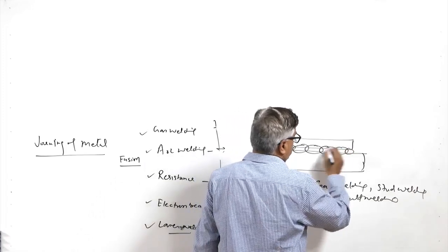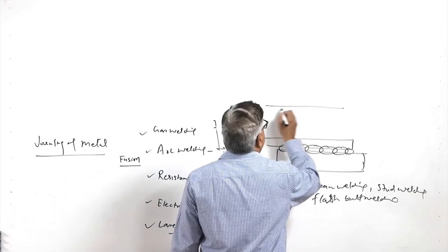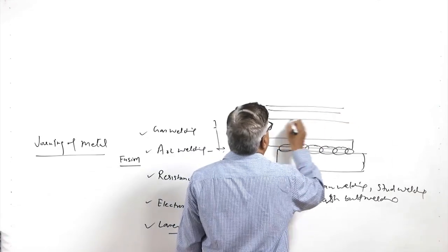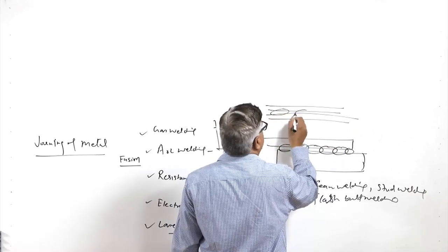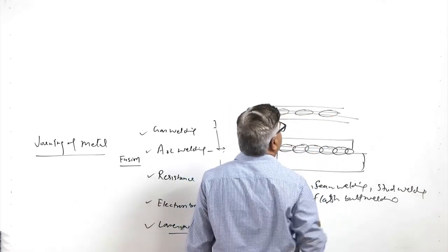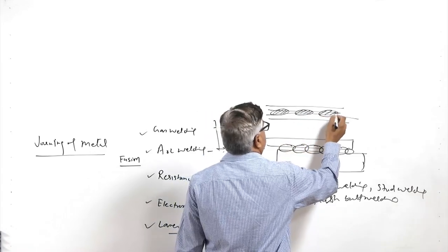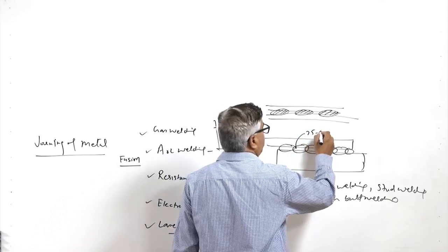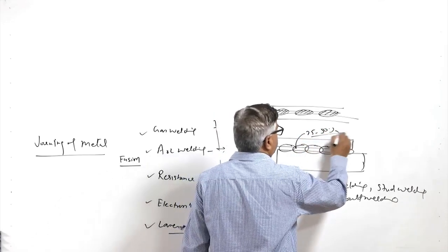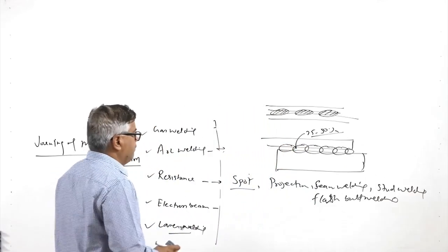A continuous seam or an interrupted seam, with interrupted spots, is also made when somewhat better strength but not air tightness is needed. In that case spots are made at some distance or overlap, otherwise an overlap of 25 to 50% can be done if airtight and leak tight joints are to be made.